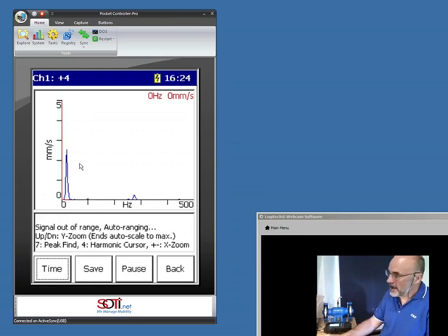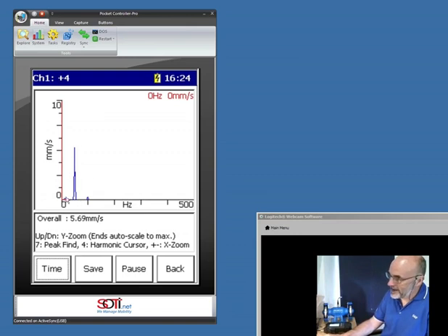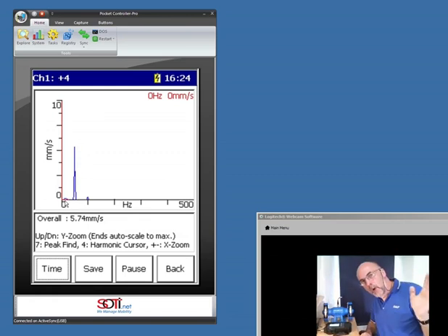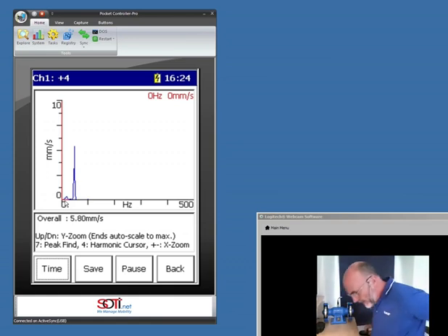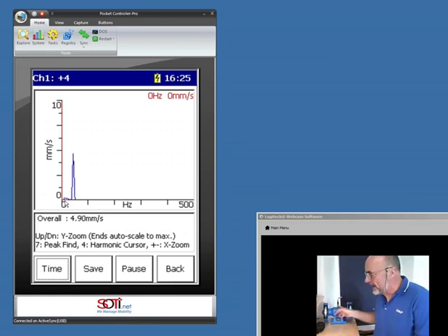In relation to the vibration coming from my machine, that seismic vibration is really tiny. So there's my seismic vibration down there. Here's my vibration coming from the machine, and the relationship between the two, one is so small, we can more or less forget about it now. Job done. Great. So beware that sensors don't just measure the vibration from the thing that you put it on, it measures planet Earth.